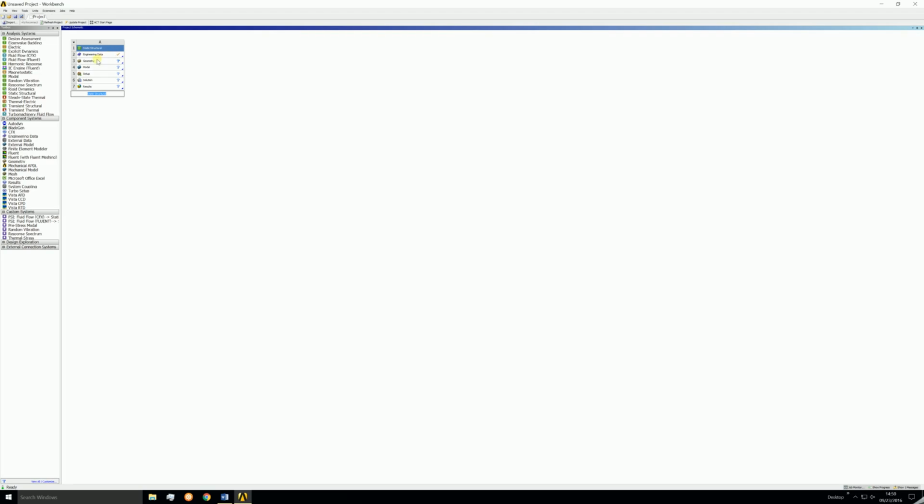We'll create the virtual steel bar in geometry and add the proper dimensions. The material is already specified in engineering data. It defaults to structural steel automatically, which is the material of the bar. Next is model. We'll mesh the bar in this section, more on that later. Setup is where we'll apply the temperature to the bar and fix the ends. We can also select the solution from that window, solve, and interpret the results. Model, setup, and solution are separate steps, but we deal with them in the same window.